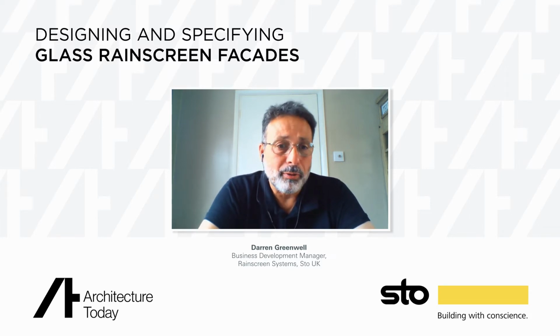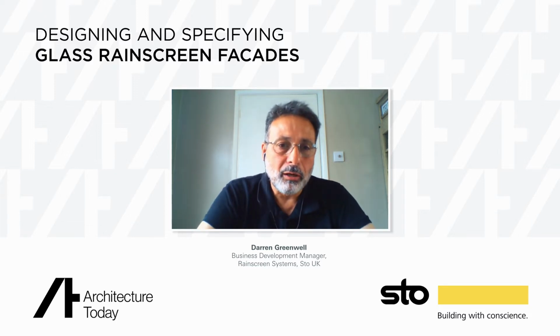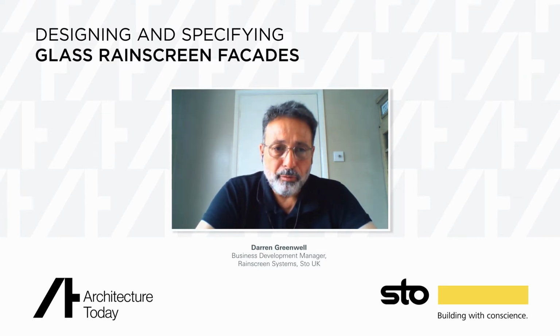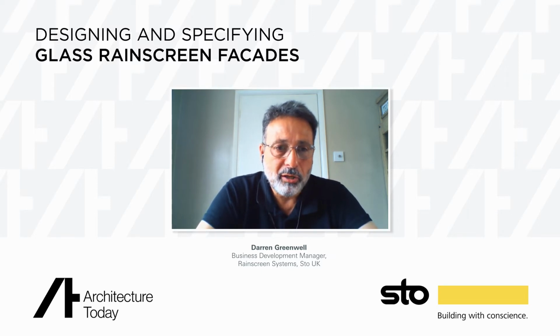Sometimes it's digital printing, particularly where you've got a non-repetitive pattern or you've got individual shapes, icons, logos, signage, that sort of thing that can all be digitally printed and then back enameled onto the glass before it's baked. So once it's baked, that's it. The logos are on the back. But yeah, we're able to provide samples. So if the person asking the question wants to get in touch with us afterwards and detail some of the specifics that they're looking for, I can advise whether screen or digital printing would be the best option, and then move that forward with them from there.